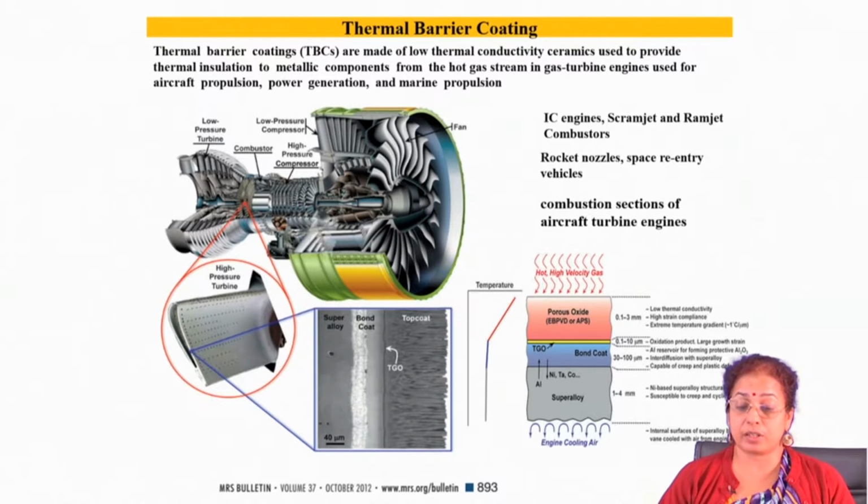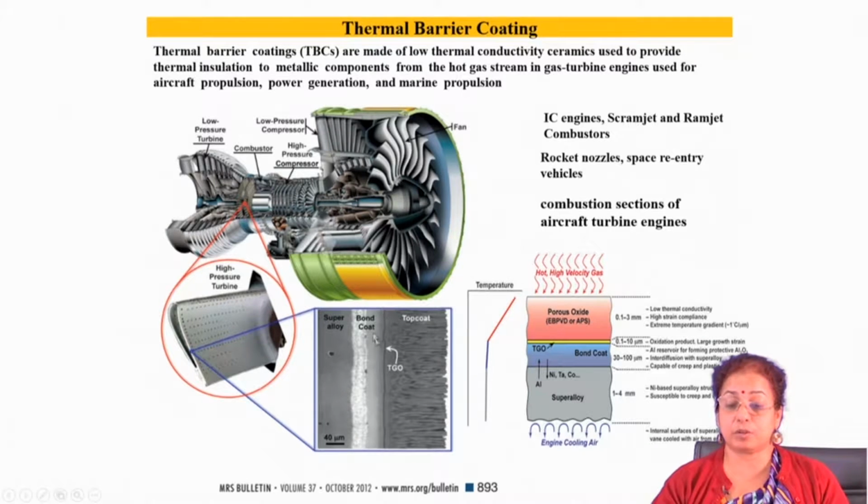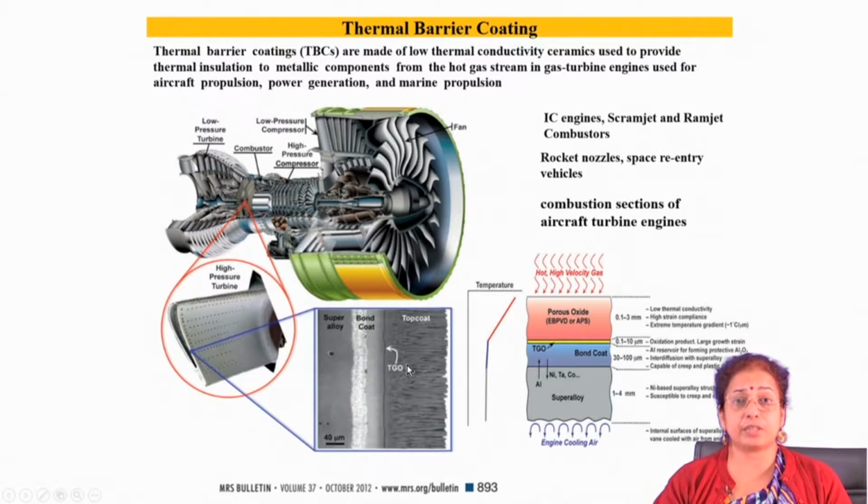So, our newer approach was to develop a graded coating instead of the monolithic ceramic coating as the thermal barrier coating, to have higher toughness and also superior properties of the coating. What we did is that we used the CoNiCrAlY powder as a bond coat, and for the top coat, instead of having the YSZ, yttria stabilized zirconia, monolithic coating, we used a combination of YSZ and